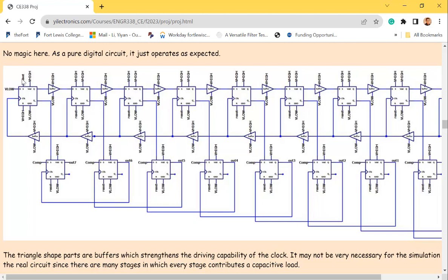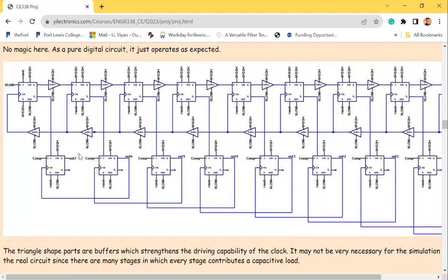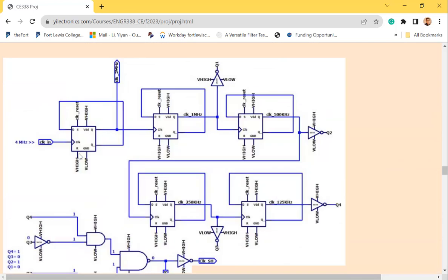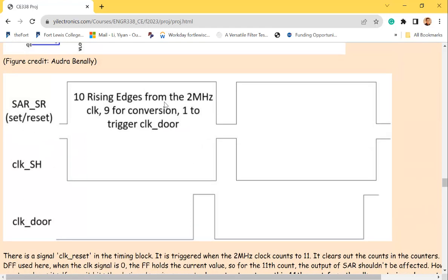That's right. So when it's holding, you want to start the conversion. And so now we want to start designing the control logic here, right? When you put it down to 0, you reset it, but at the same time you sample it. After that very short period, you don't need this one to be very wide, right? You don't want a 50% duty cycle. It's a waste of time. You just reset it, give a logic 0, it gets the work done, and then you just want to move forward. Same for the sample and hold. You sample, you hold it. You can actually make this one narrower, but this is just a concept of the cycle.